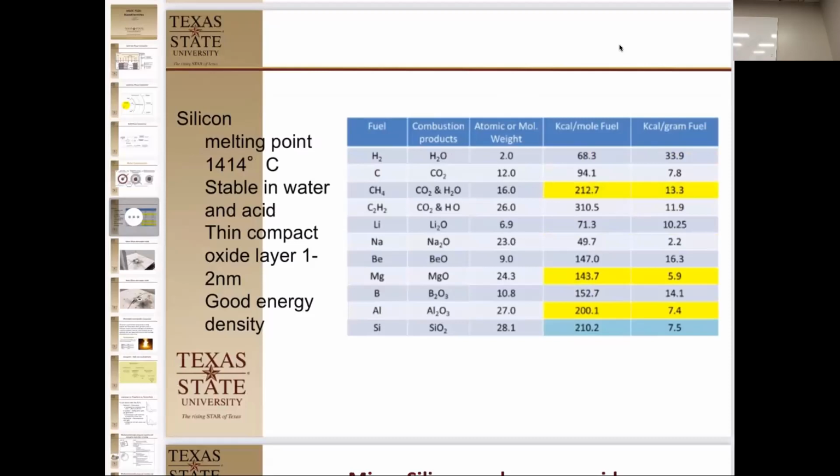There is an advantage to silicon though. Silicon creates a very thin oxide layer, 1 nanometer or less. Think about all your perfectly level, crystal face wafers you get. You can have them with zero oxygen, move them around from here to there, and put your layers on there when you want them, or etch it so you have an oxide layer on there.